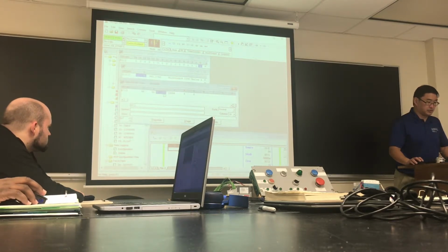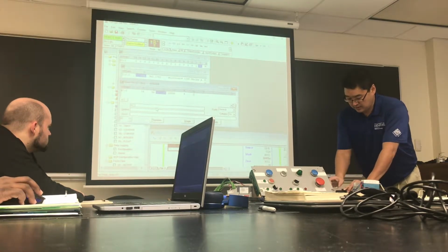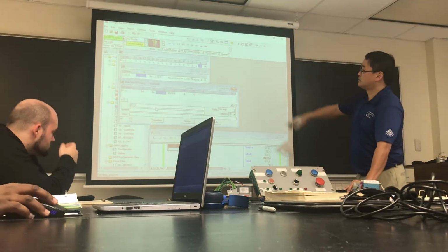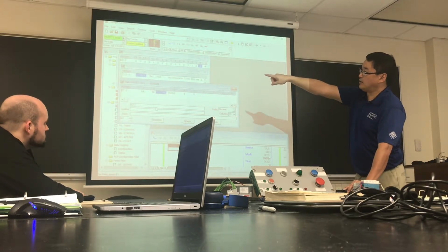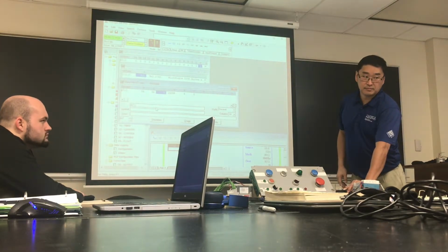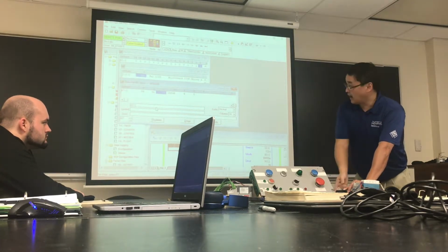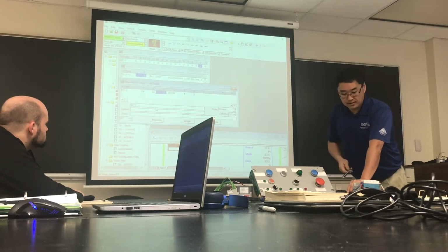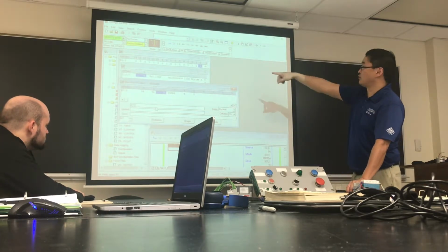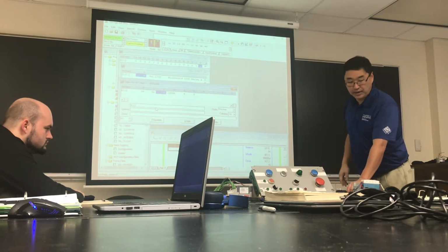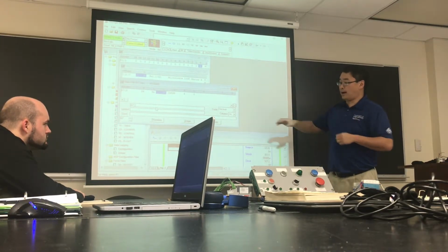Yeah, N7.2. So N7.2 there, right? You'll notice N7.2 is 9, which is what it should be. But the input value is 521. 521 is not the right answer because if I remove that additional sensor, now I've got the correct 9, because I only care about the first 4 bits when I try to do my BCD conversions or whatnot.